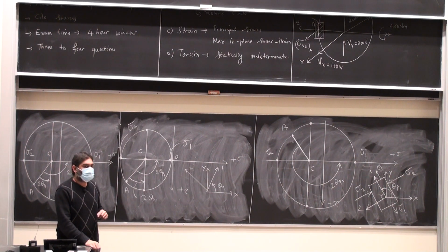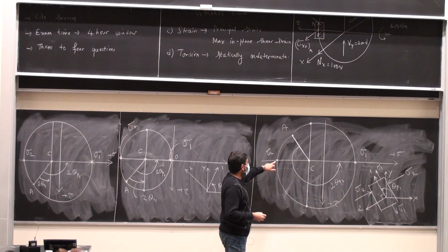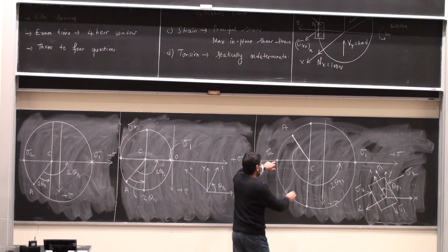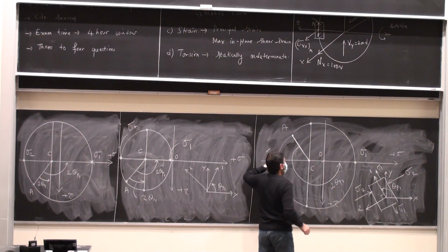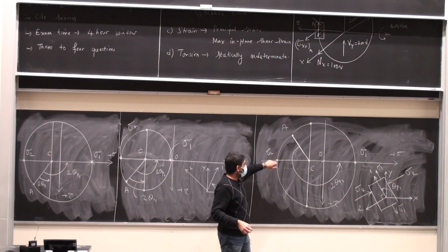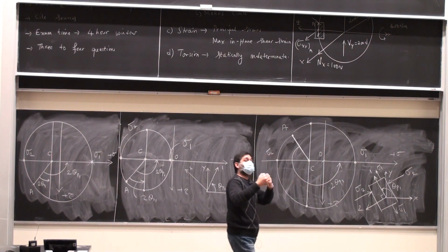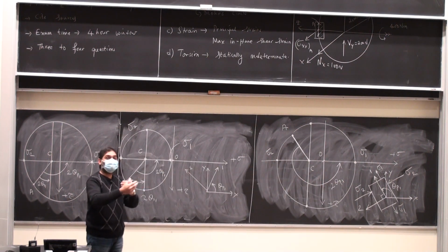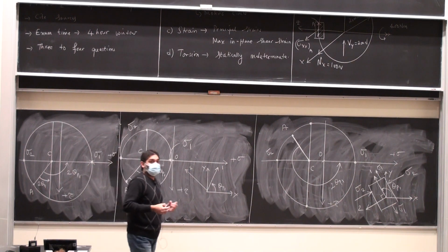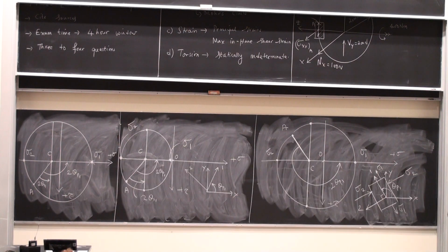How did you determine that sigma 2 was compressive and sigma 1 was tensile? From the negative. Okay. Right, because this is the origin, right? That's positive sigma. This is negative sigma, so this is going to be negative sigma 2. So sigma 2, you see, is actually in the sense of what we typically call a sigma 1, right? It doesn't look like a typical sigma 2. But what's typical, what's not, who knows. It has to depend on the orientation. You see that?